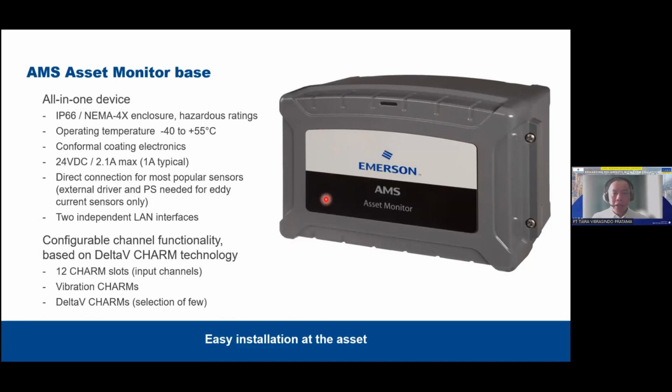So again, just to show, it looks like a typical junction box here. And within this box, you have the cards inside. And the cards are the vibration card. It can be the process data cards and so on. So as I mentioned earlier, IP66 rating, NEMA 4X is very suitable for outdoor installation.